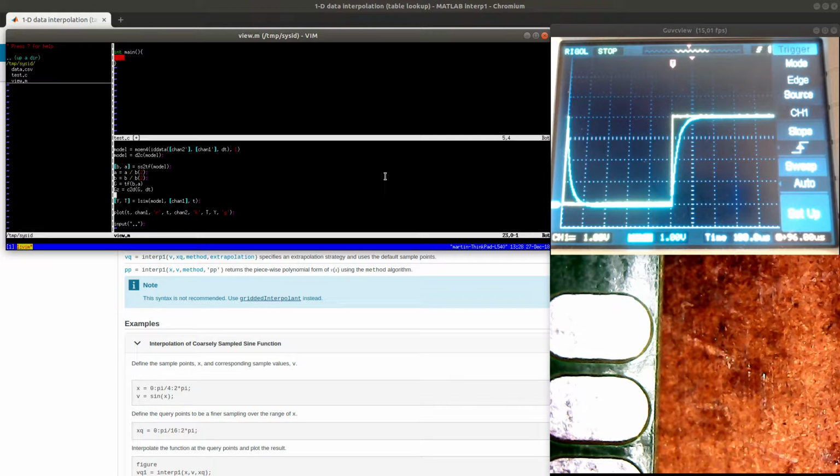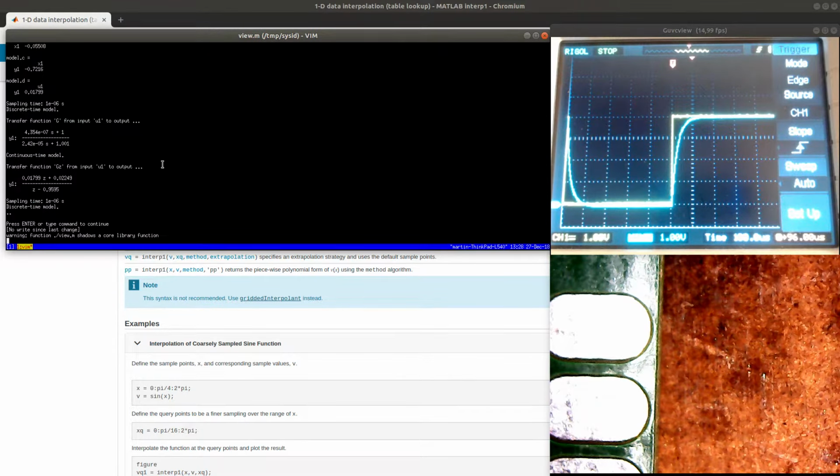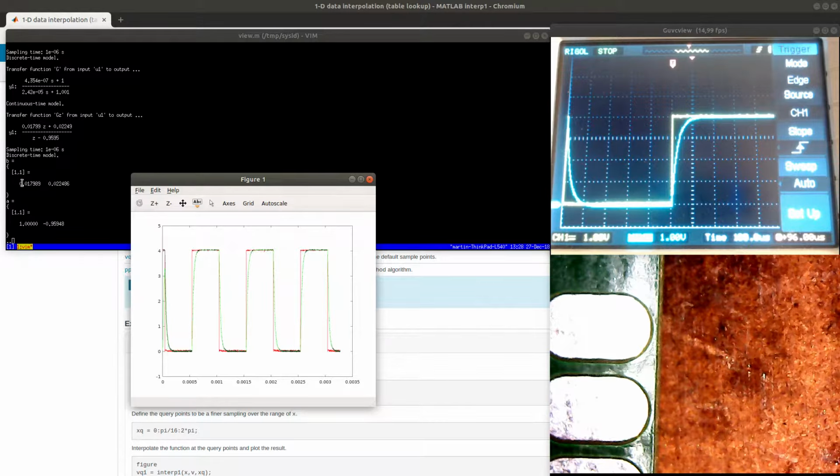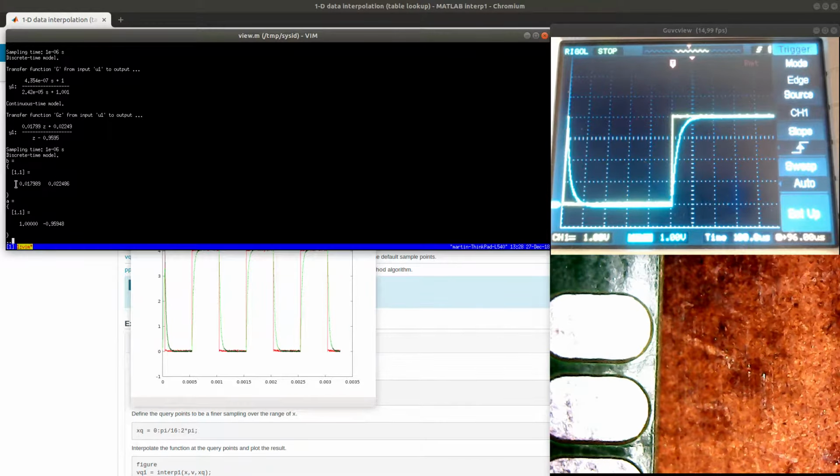And also because the values that are pre-printed by Octave are not real, they're rounded, it's better to also take the B and A and extract them using tfdata from B and, let's see, from Z, like this, so that we get the more precise values of the coefficients. So this would be the coefficients of the previous, let's see, this would be the x.